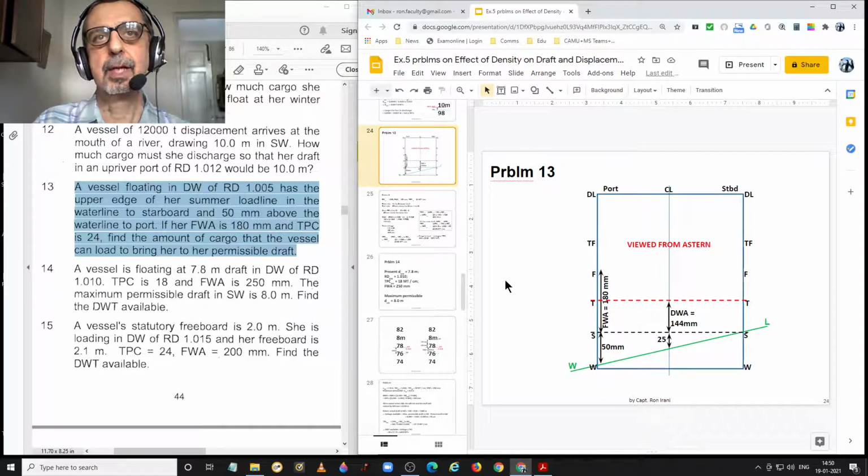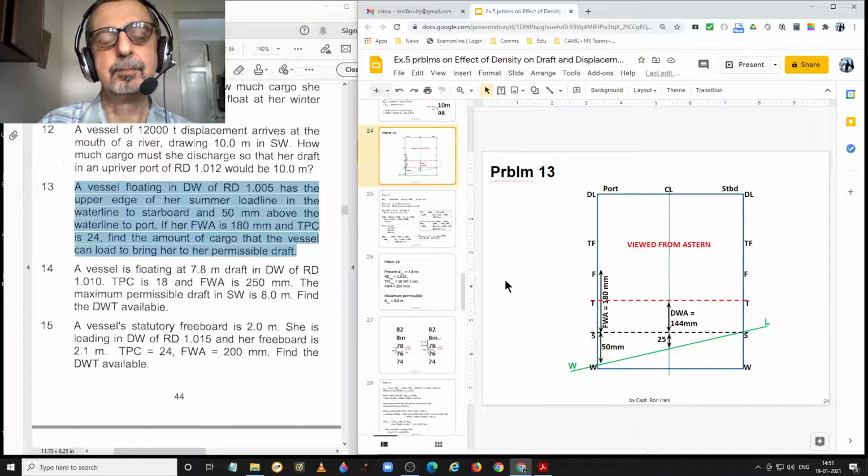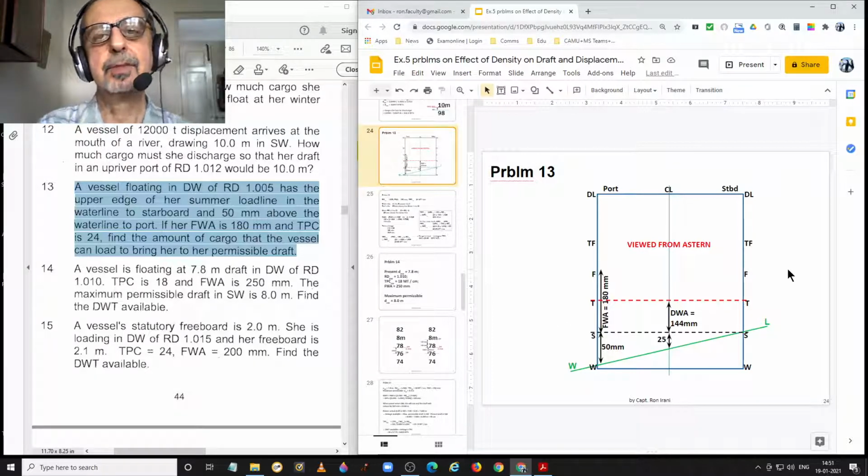The actual load lines that matter are virtual load lines found on the center line of the ship. Hence, whatever we see on our port and starboard side hulls is to be virtually transferred to the imaginary load line on the center line of the ship.